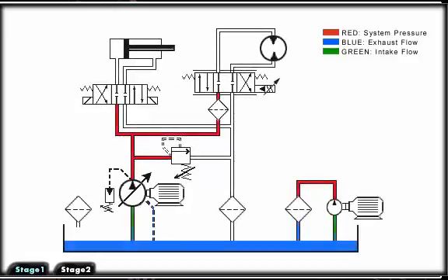Filter placement is critical for maintaining acceptable fluid cleanliness levels, adequate component protection, and reducing machine downtime. Filter breathers are critical in prevention of airborne particulate ingression. As the system operates, the fluid level in the reservoir changes. This draws in outside air, and with it, airborne particulates. The breather filters the air entering the reservoir.